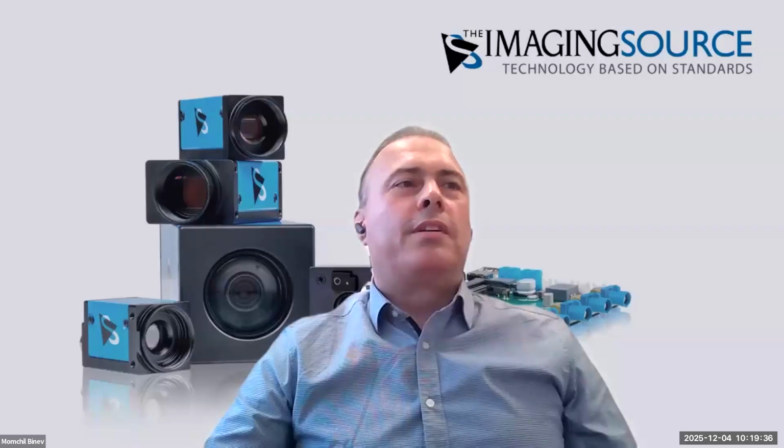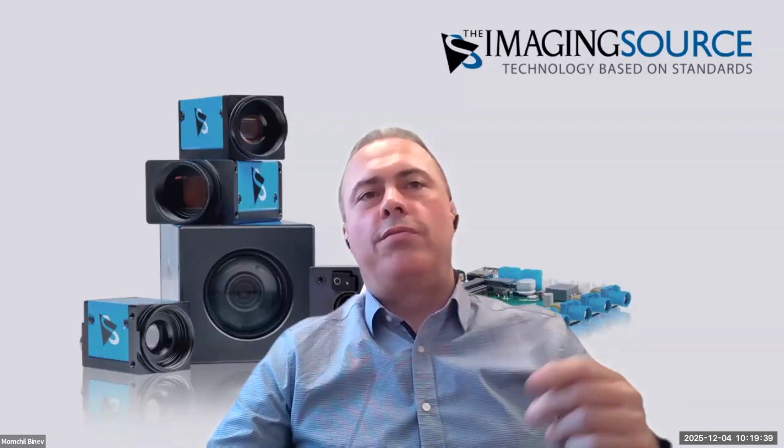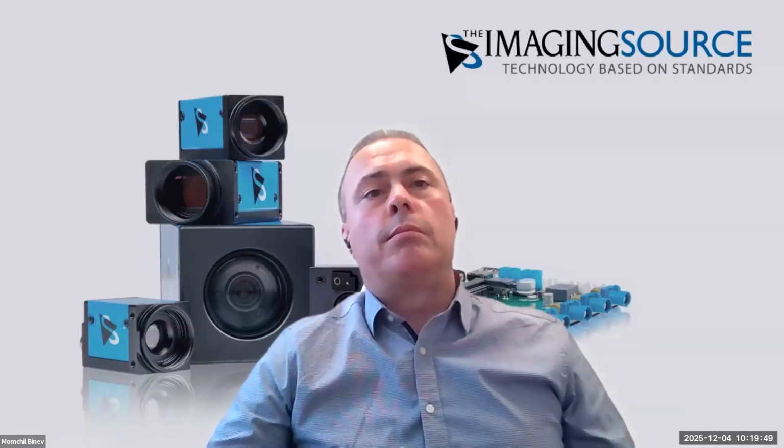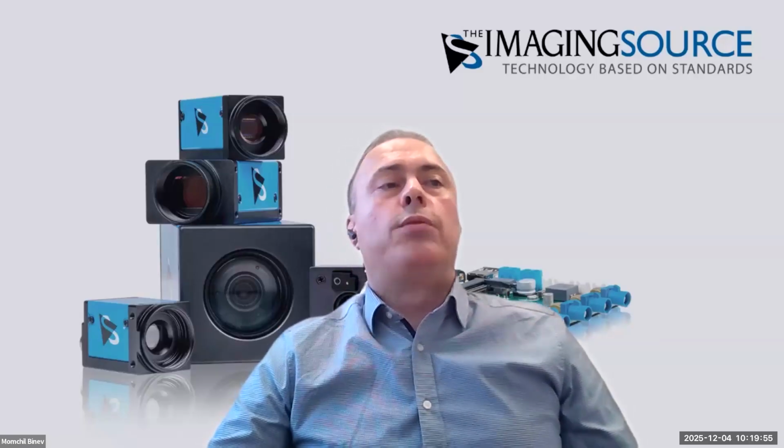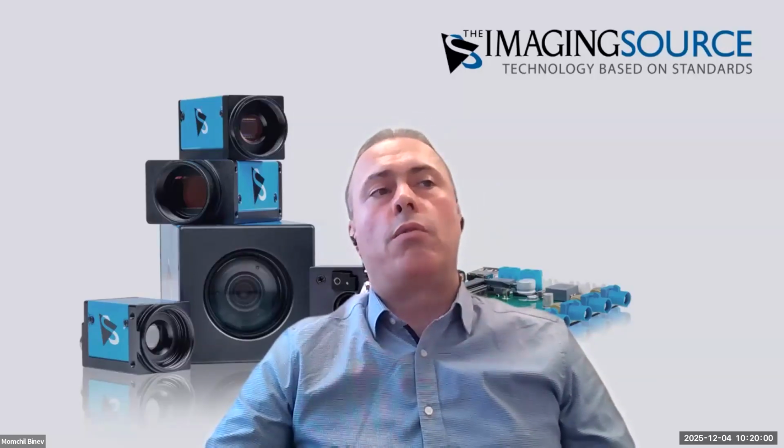Are real-time, below 100 millisecond video streams generally possible with your offered product range? Absolutely. As I said, it depends on the technology. If you look for real-time functionality, I will always recommend using MIPI or GMSL2 or FPD-Link, because then you have the direct connection to the image signal processor of the SOM. If you decide to go for USB or GigE, you typically copy some data. So this is not as real time as classical MIPI CSI-2 interfaces or derived interfaces.